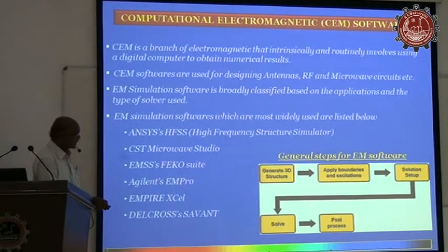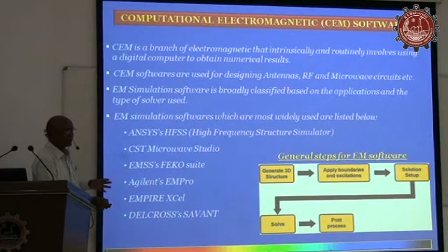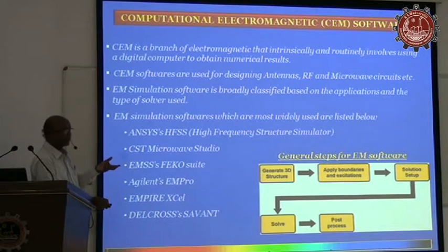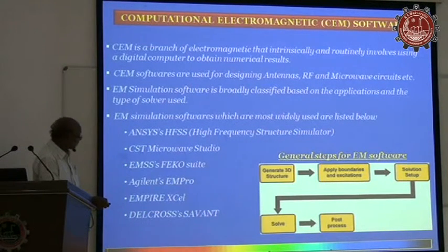The total data is available, which is why it takes more memory. You can manipulate it. Suppose you want to plot gain versus frequency, you can plot it. If you want to plot the radiation pattern, you can plot it. Any way you want to present the data, the post processing is very good in HFSS. Most of the time we are using HFSS.